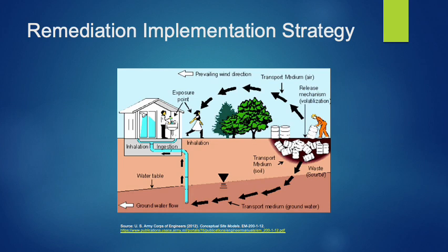If we do have a situation that requires mitigation or remediation, the first thing we do is develop a conceptual site model, which will allow us to come up with a remedial implementation strategy. A conceptual site model factors in the contamination that may be present, the site use, the potential site use, as well as several physical characteristics associated with the site, including depth of groundwater, direction of groundwater flow, and soil type, or bedrock type. We factor all of these into consideration and try to determine how people may be exposed to contamination during site use, either currently or for a proposed use.